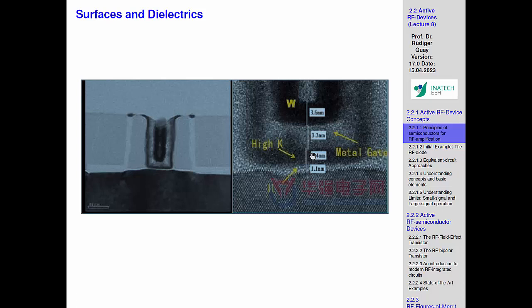And the digital people would mainly talk about the on-off ratio. So keep that in good shape, because when you don't do that, you lose. If you keep the oxide thickness large, then you cannot really turn the transistor off nicely. It's a direct consequence, because you cannot get a sharp control towards off.